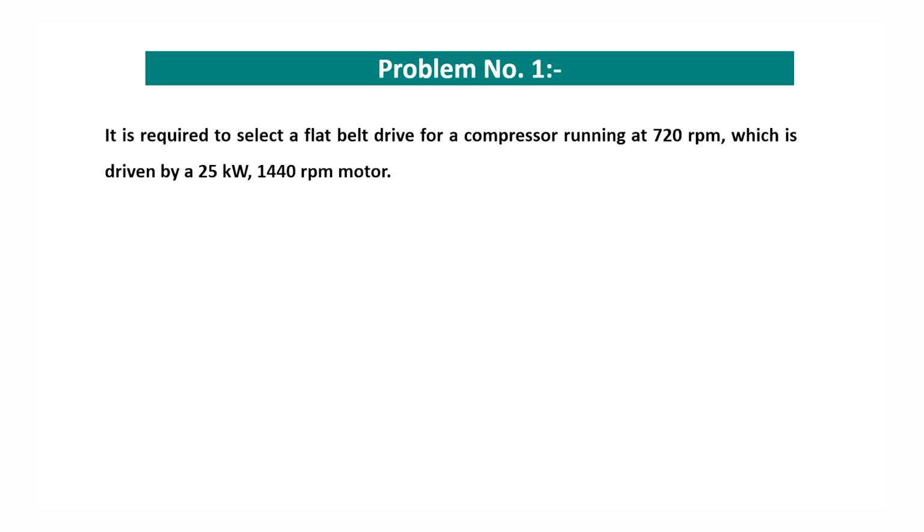It is required to select a flat belt drive for a compressor running at 720 RPM, which is driven by a 25 kilowatt, 1440 RPM motor.